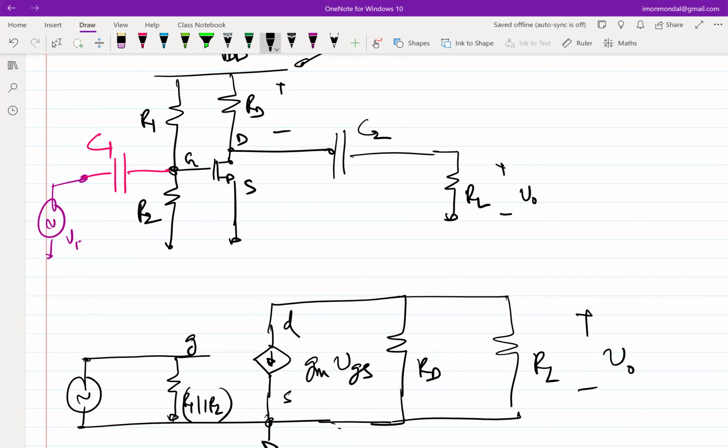When I say size it properly, I mean I size it in such a way that it acts as a short circuit at the signal frequencies. Right? If it's infinitely large, for example, at any non-zero frequency, it will give you a short. But for a frequency of omega naught, we have to ensure that the time constant is large enough so that the capacitor voltage doesn't change appreciably within one time period, right? So that's why the time constant requirement comes. We also saw this with respect to the Bode plot, with respect to the magnitude plot, why that requirement arises.